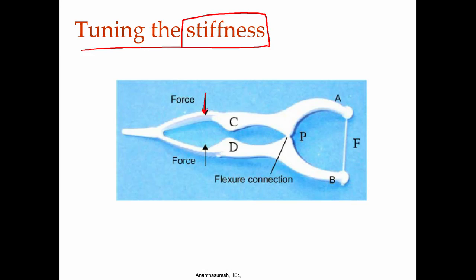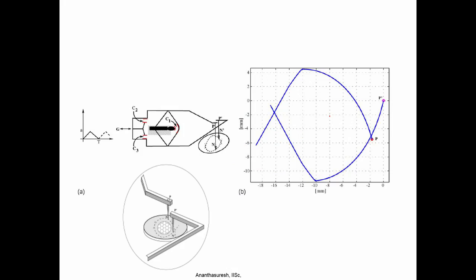Okay. So, here as I showed, when we apply force over here, this is where there is a gap. That gap closes. Initially when I press, this point will move this way, and this will become taut. By that time, these two would have touched each other. Once they touch, there is a stiffness increase, and even if you apply more force, it doesn't pull more force this way and break it. So, that is the advantage of having intermittent contact.